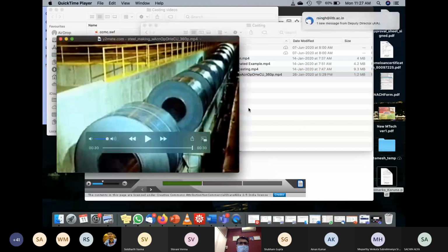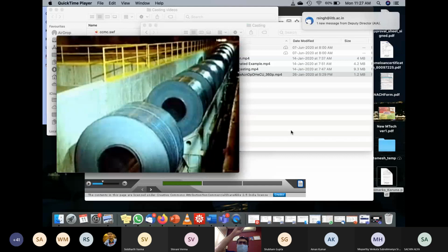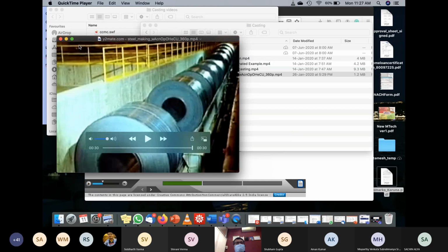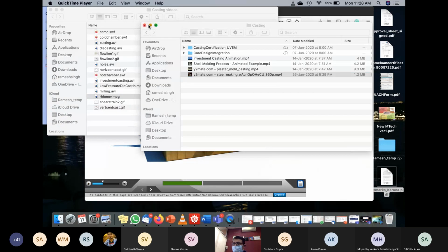So continuous casting basically means that when they pour the material, it freezes and is rolled. So you pour the material, it freezes, and you can roll it right away. You don't have to cast billets out of it. You don't make billets, right? So then you can do it continuously, keep on casting. As you pour it, it solidifies, and then you roll it in the hot condition, and then keep on. So that's called continuous casting. You don't have to create discrete billets out of it. Get me? So that's what continuous casting is.